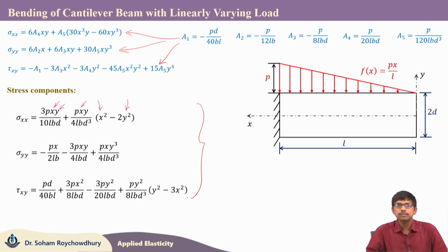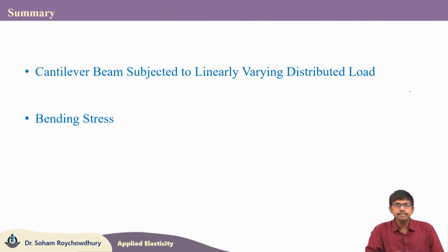Note that we are able to satisfy all the boundary conditions except one, that is, on the free edge, tau xy, we were not able to force that to 0. All the rest of the conditions are satisfied. Now, following Saint-Venant's principle, these results are applicable for the region apart from the 2 edges x equals 0 and x equals L. So, in total in this lecture we discussed the bending stresses for a cantilever beam subjected to linearly varying distributed load. Thank you.